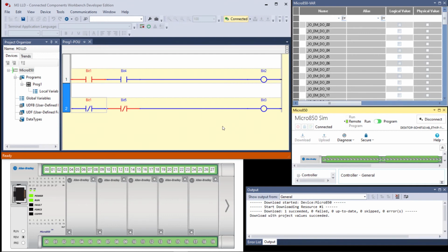Which instructions are true? Direct contact bit 1, right there. Yes, it's true because it's red. Direct contact bit 4, it's false. So bit 1, read bit 1 on, true. Read bit 4 on, false. Now, if you read this one, it's false, and if you read this one, it's true. On the next page, we ask you again, not about true and false, but on or off.